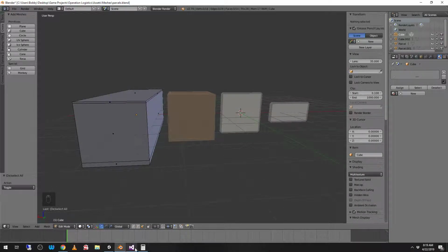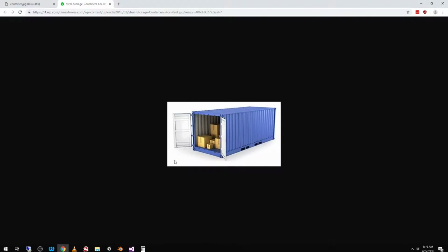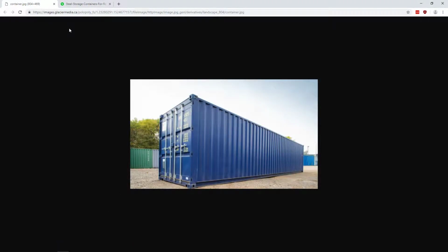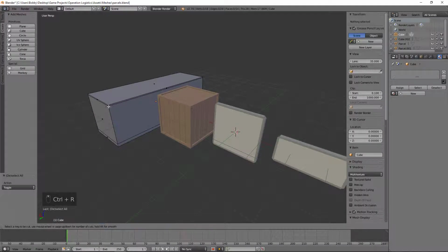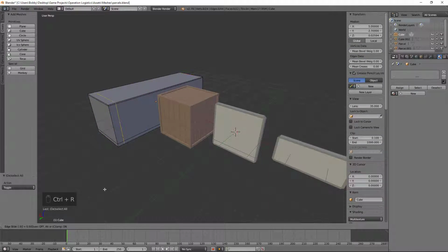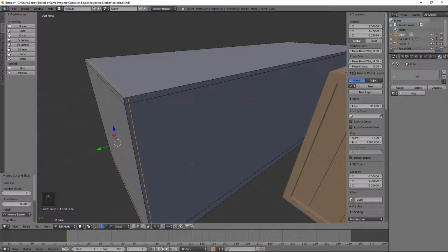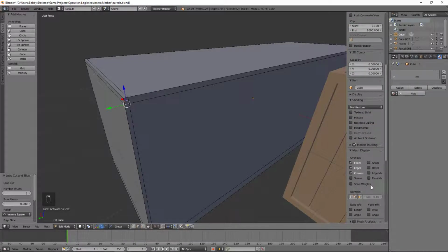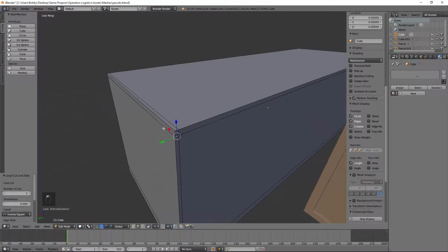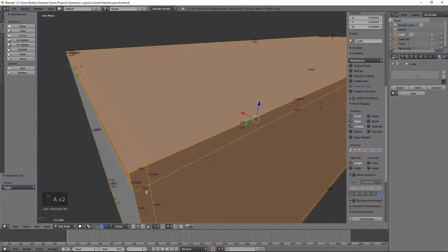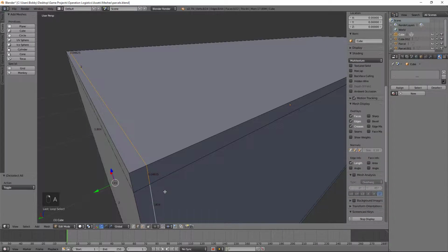Back here, we need to look at our reference again. Yeah, there's going to be this same lip back here, I think. So let's just go ahead and create that quick. About 0.95. That's too big. 0.99. We'll make it be the same lip size in a moment. So this is an edge length of what? I don't know, it's kind of hard to see. 0.03. Right here. It needs to be 0.04625 to match up.